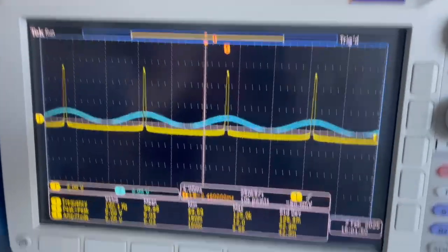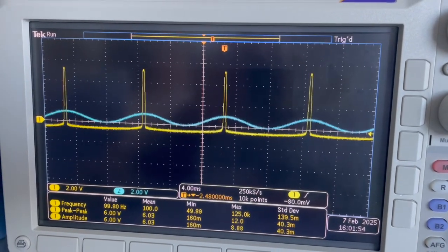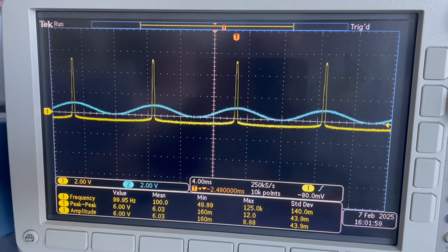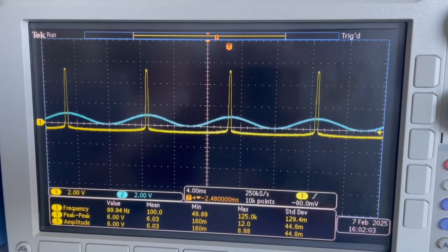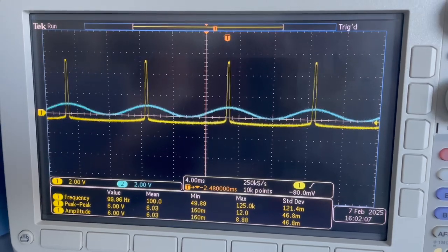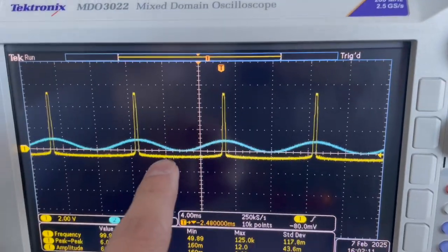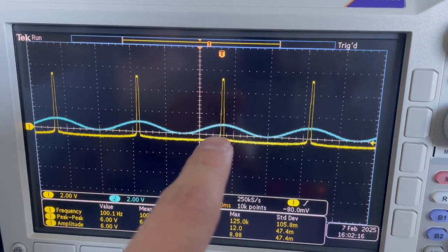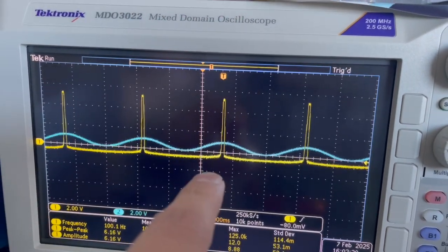So what we have to actually obtain: the blue line is this input signal. So we're feeding the sinusoidal signal of 1 volt from 0 to 1, and in output we're getting this yellow line. So basically what this logarithmic amplifier is doing is actually suppress big signal changes. And as we can see, when sinusoidal line is increasing, it suppresses changes. So we don't have any changes, only up to when it reaches the maximum, then it goes up exponentially and comes back.